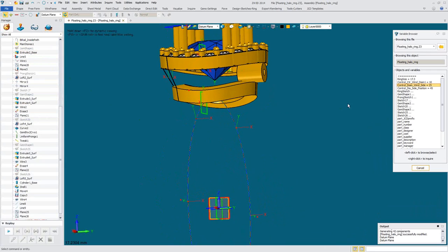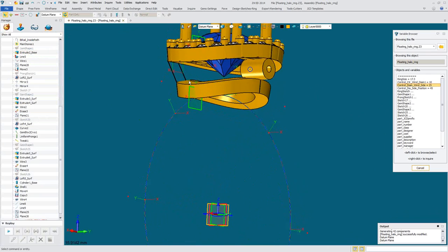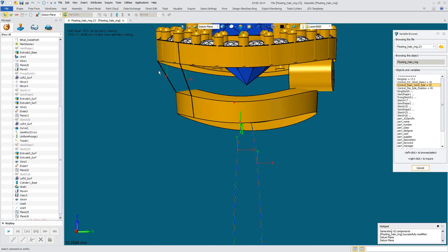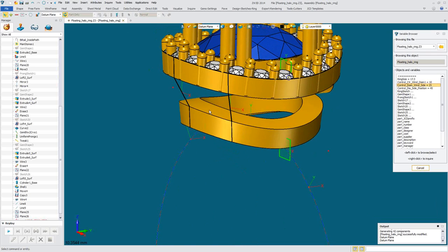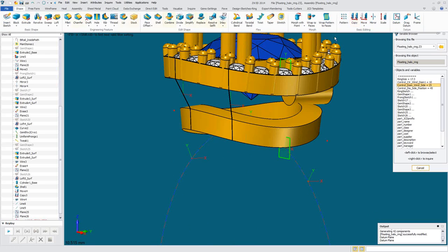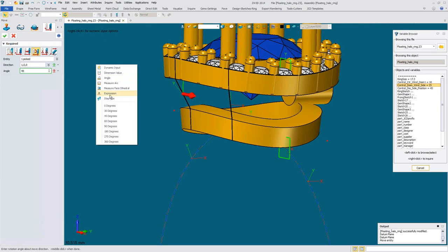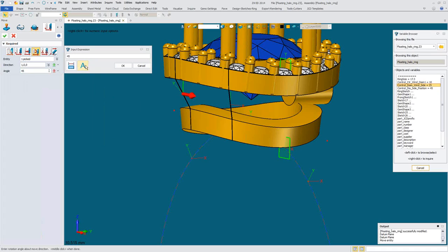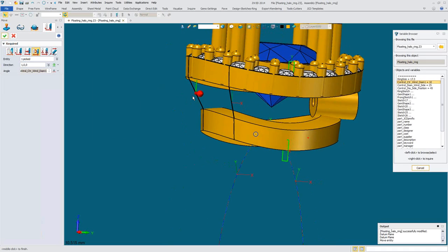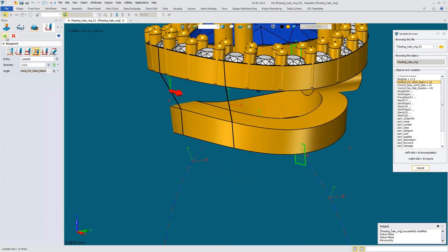Okay, now this other control that I put in here is for creating an angle. If you want to tilt the diamond and you don't want it going straight on, I could use this one control for both of them. All right? So, for example, shape, move, rotate. This datum plane, the direction is this x-axis. This angle, right-click, expression, left-click on this button, and pick this other control and approve it. All right? It's probably not what we want, but I want you to see how to play the game.